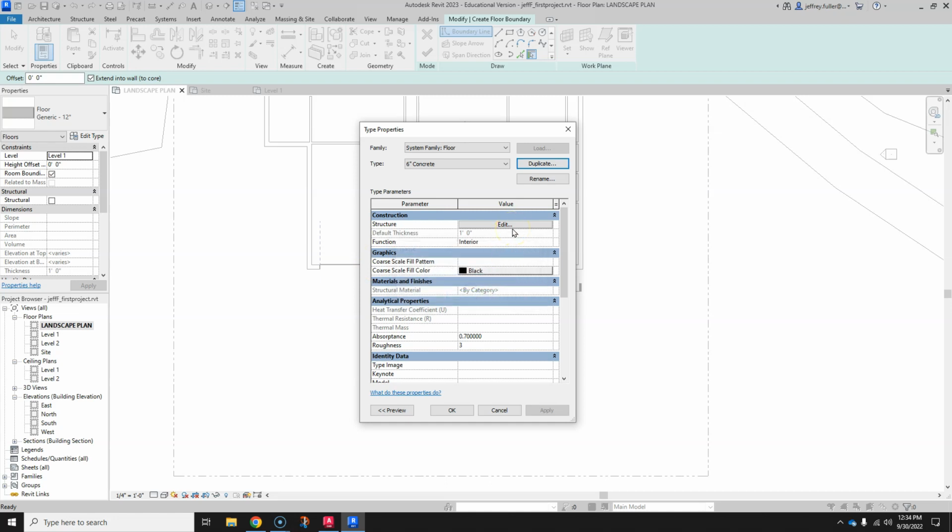Now, in reality, typically your driveways and sidewalks are 4 inches, and you can annotate them that way on this drawing or on one of these drawings. You can annotate them as 4 inches, but in your actual fictional world here inside of Revit, you can go ahead and draw them in at 6 inches thick or what have you. Because what we're looking at is just kind of for photographic value.